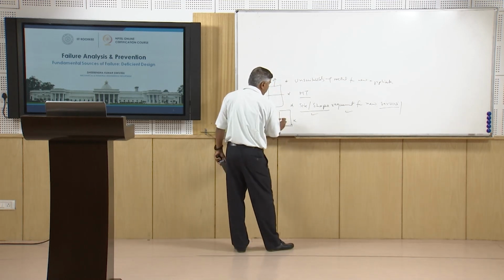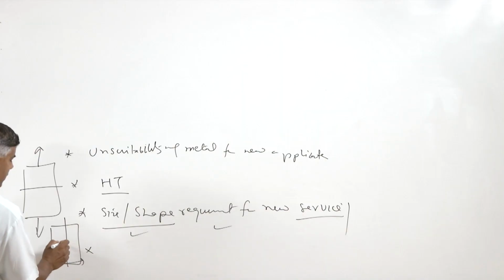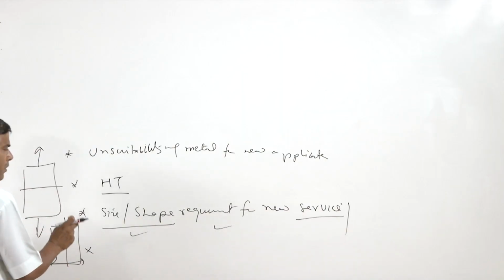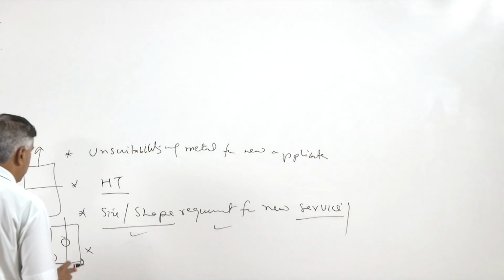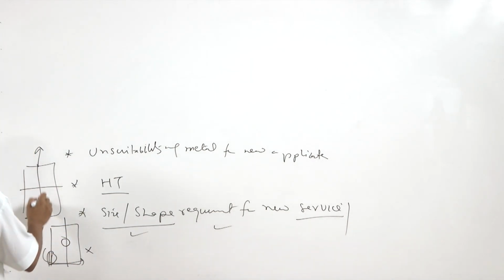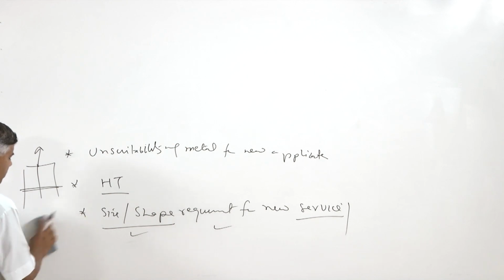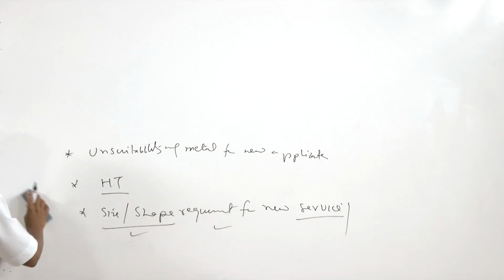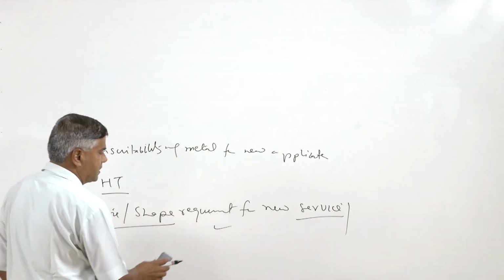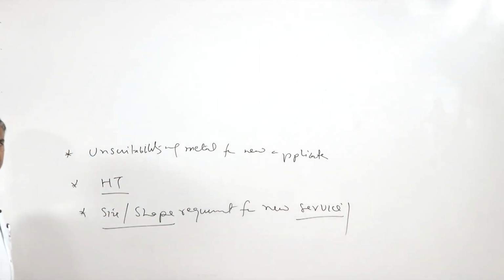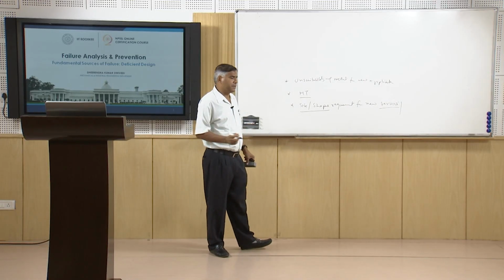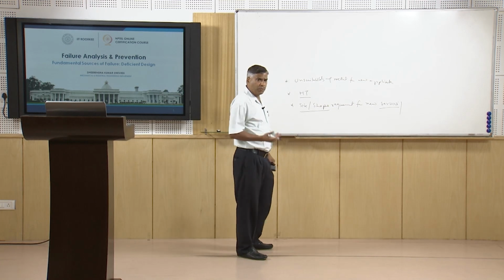So, in case of the torsion, the stresses in the core or near the center are 0 or very less as compared to the case of tensile stresses, where they are uniform across the section. So, depending upon the type of stresses, severity of the stresses or complexity of the stresses, the different sizes and shapes may play a crucial role.